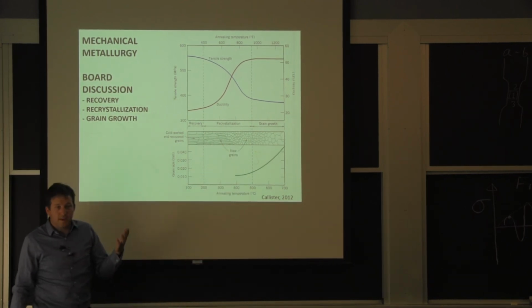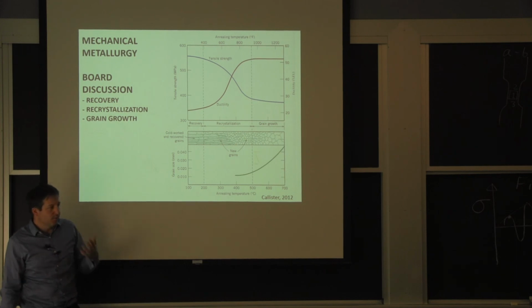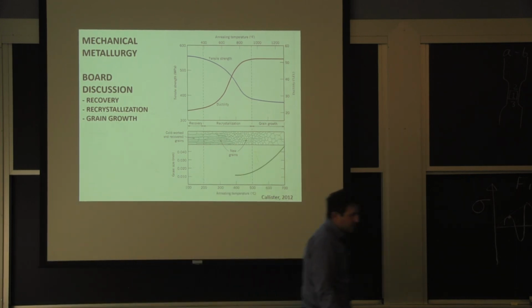The goal is great, because if I'm trying to deform from these billets that we've talked about, trying to go down all the way to something like this, if I don't have recrystallization that gets rid of my dislocations, I'm going to have to work very, very hard. So when I make those, normally I'm in a mode that I keep recrystallizing new grains. And that keeps the force required to make the part relatively low.